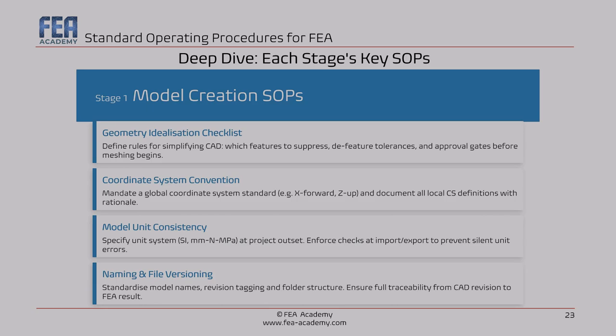And why the sign-off before meshing? Once you've spent 4 hours meshing a complex assembly, the psychological cost of going back to fix the geometry is huge. So the sign-off gate enforces the right sequence.